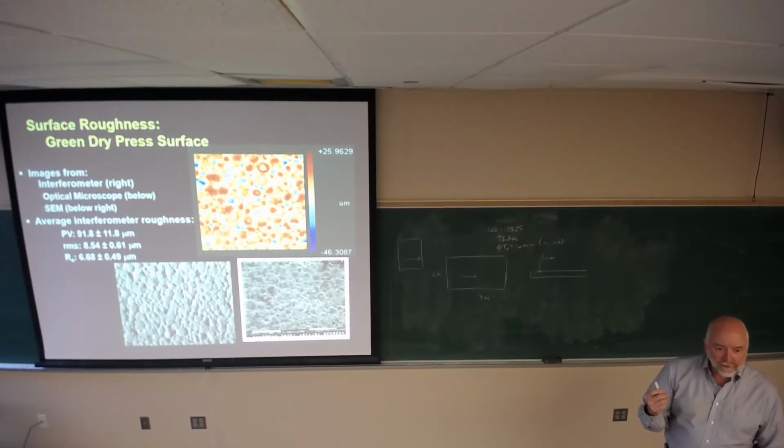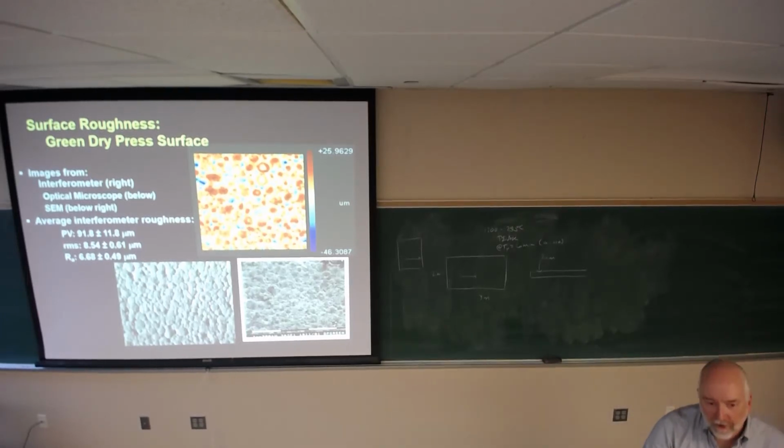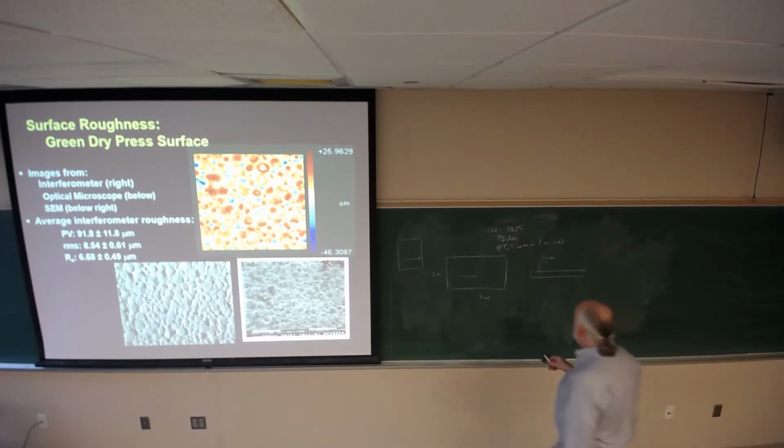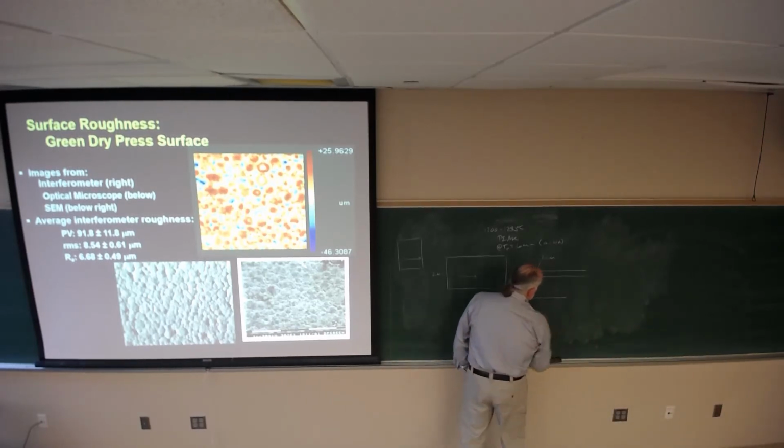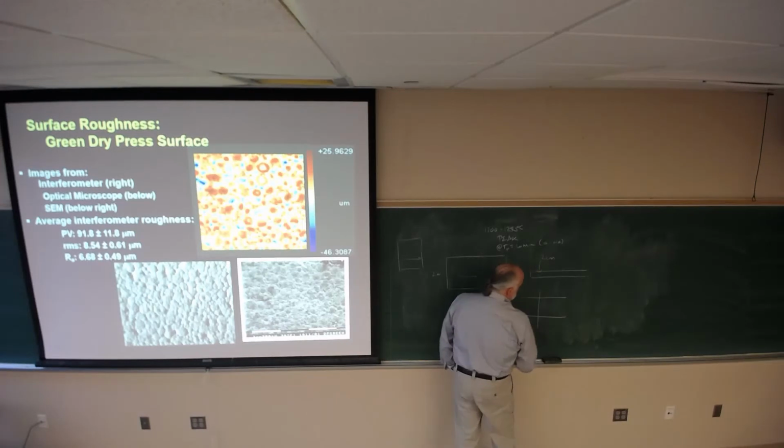You know what tempered glass is? So what they do is they rapidly cool the surface of the glass to let the surface solidify while the inside is, we call it the jelly center, right? That's what I call it. And so then that interior volume is contracting, and by doing so, you end up with a glass piece, and the stress profile looks like this, right?